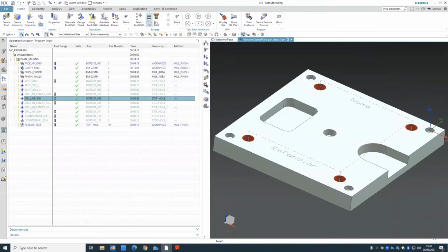All right. Okay. So once you increase the number of Z moves, it's good. But there are various things you need to consider, to be honest, because with the G00, you're putting pressure on the machine. So both actuators work together. You don't want to have so many unnecessary G00 rapid moves. There's no point in it. So you have to balance everything.